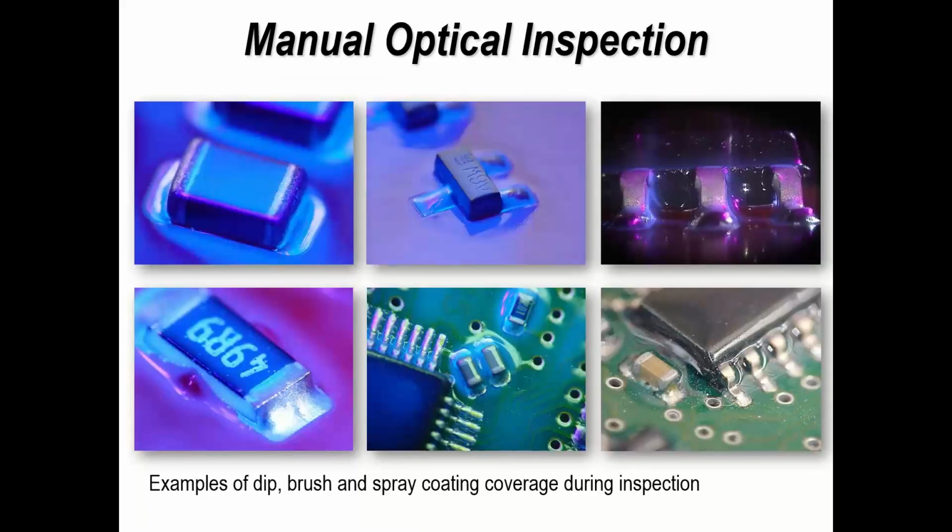So what we're trying to achieve with our coating process, whatever it might be, is a fairly consistent coating. It's coating all the surfaces to protect against any corrosion or damage on the printed circuit board due to the environment it's going into. You want to minimize the possibility of bubbles forming within the coating, which reduces the insulation gap between terminations. And that material must give us some form of indication that it's been applied correctly.